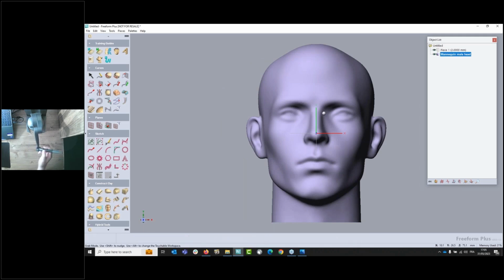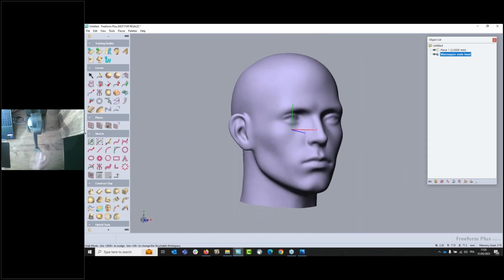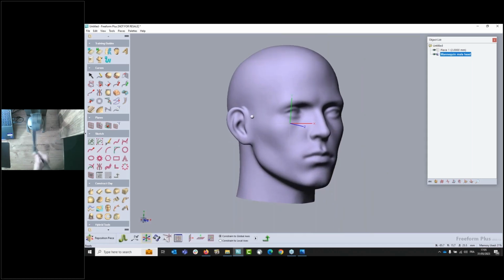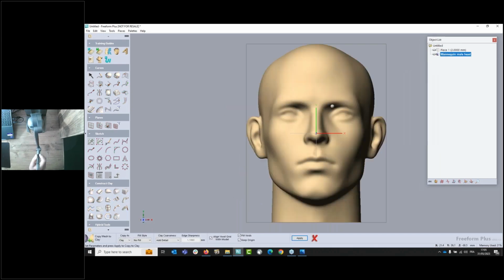My 3D device will allow me to fully rotate around the object, zoom in, zoom out, of course. And the first thing I will do, I will convert this mesh object into a clay object, a digital clay object. For that, in my object list, which contains every information about my project, I will just click on the icon, go in Mesh Utility, and ask to copy my mesh into digital clay. Here in the Dyna bar, which shows every time the active tool's options, I will choose my level of detail. Let's say 1 millimeter will be enough in the beginning. Then I will apply it.